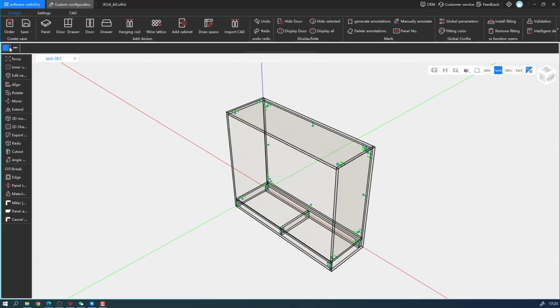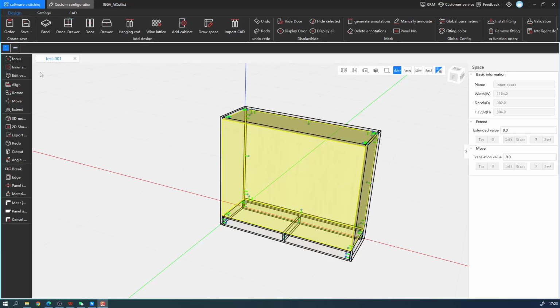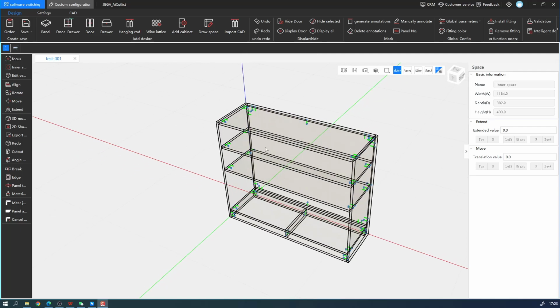You can see at the top part you have this tool. And for this tool, let's change to cabinet select. Double left click the inner part. Then you can left click here to add the shelf for you. And double left click, and this is the system part. It will also directly add a shelf for you.